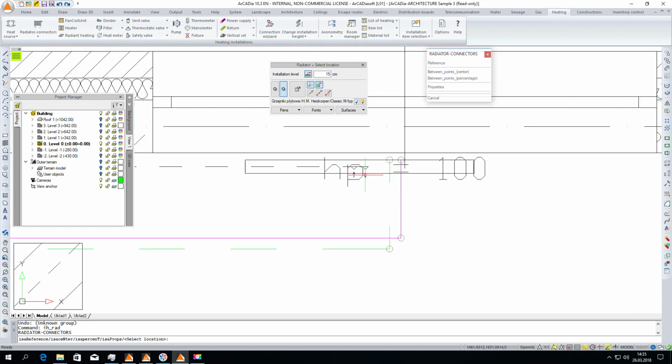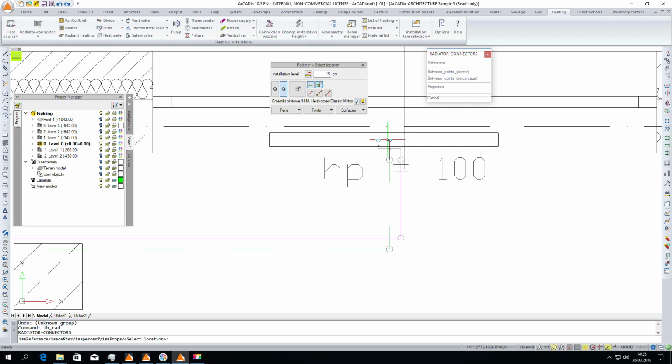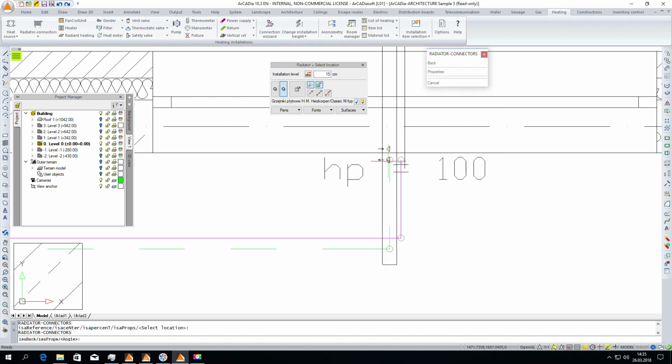As you can see, we hold the radiator for the return, that is, the arrow coming out of the radiator, so we have to put a return over the return pipeline. We unmark the function of the import from the element, turn the radiator over, insert the power supply and return.